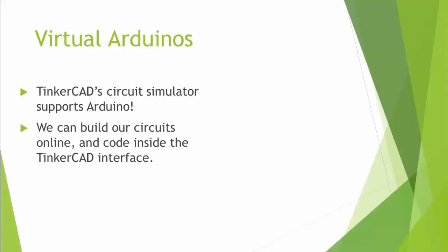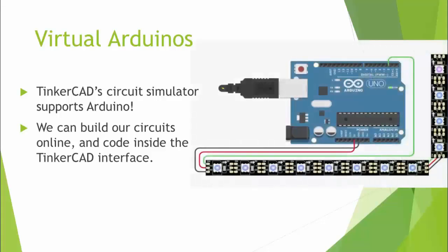So you can start to build more complicated circuits now, code inside the Tinkercad interface, and send your code to your virtual circuits, allowing you to execute control of NeoPixel LEDs in this case, or what have you, and seeing what your program will look like. So if you're ordering parts and waiting for them to arrive, you can develop your code and test it in a virtual environment.